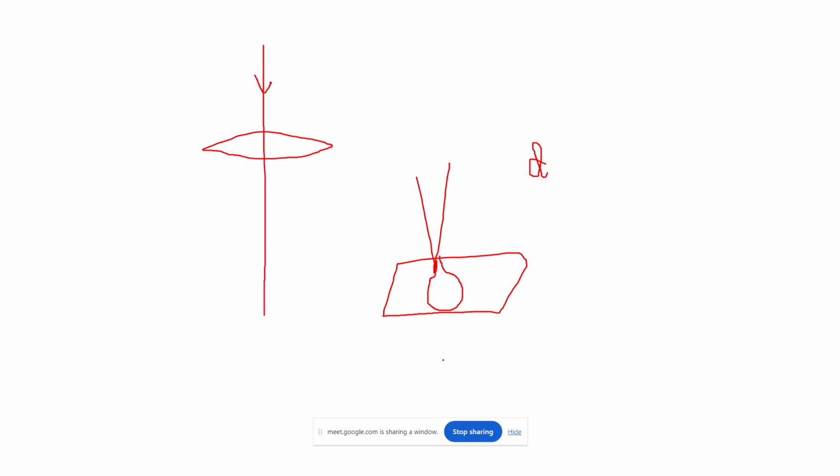Depending upon the detector which you are using, suppose this is your specimen and your detectors, this is scanning, this is not transmitting. So scanning is done here like raster scanning, from this point to this point, and then again from this point to this point. So it will do a scanning. This is known as raster scanning. In this, the electron beam is not transmitted through the specimen, so it can be thick enough, because the electron beam is only